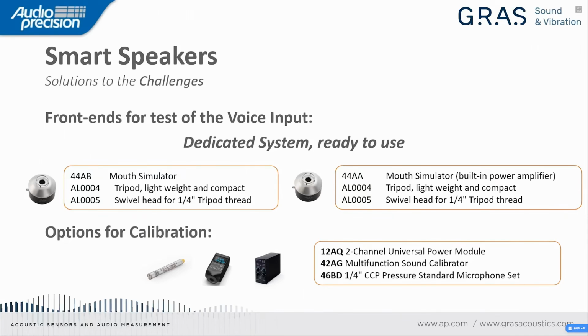For doing calibrations of these, you need a reference microphone. A reference microphone which will be placed in a test jig in front of the simulator, simulating the mouth reference point at which you made your calibration of the simulator.